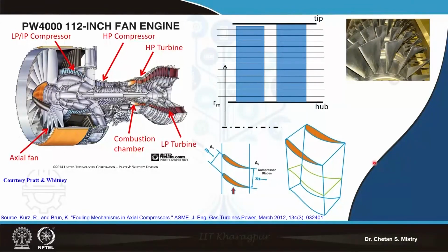So here in this case we have, say, two blades. These are the two blades which are being arranged. Here if you look, we have the leading edge and the trailing edge. This is my leading edge, this is my trailing edge, and within this passage I have my flow that is getting diffused, that has a diffusing shape. If you look, we have a larger area and a smaller area. Let me put this in a way.